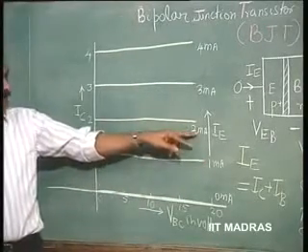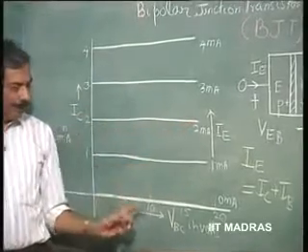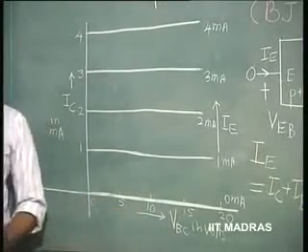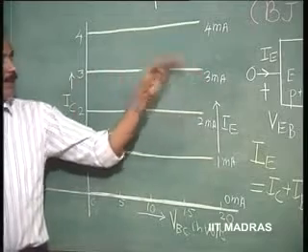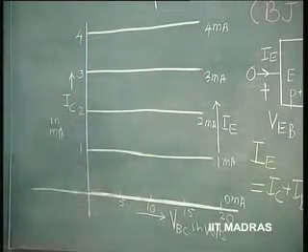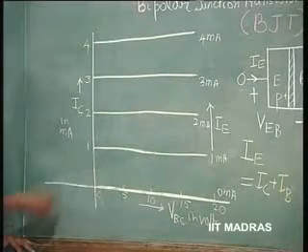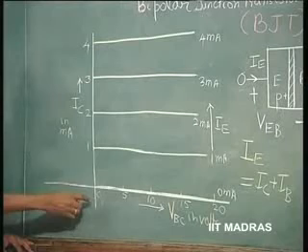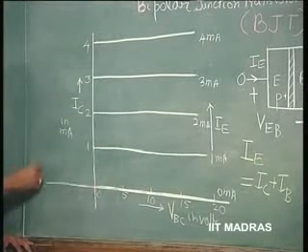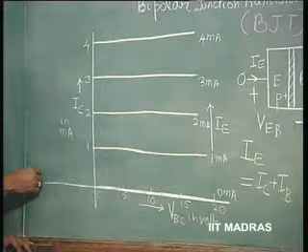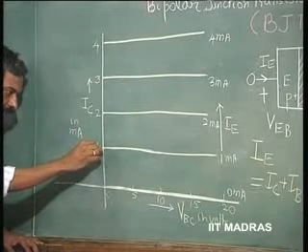If it is 2 milliamperes emitter current, the collector current remains constant, independent of the base to collector voltage, which is the reverse bias voltage in this. It remains constant at 3 milliamperes, it remains constant at 4 milliamperes. Now, strictly speaking, beyond this point, this is the point where VBC is equal to 0. Beyond this point, the transistor is said to be in the saturation region. Actually the current will start falling.